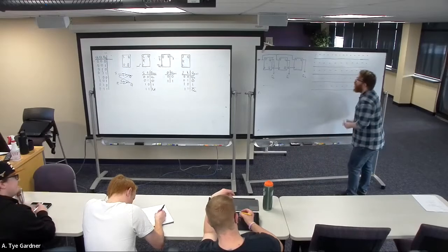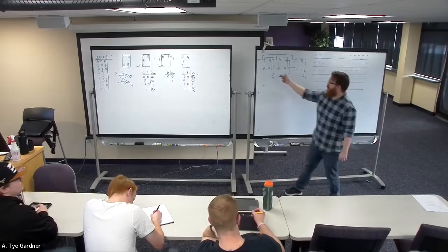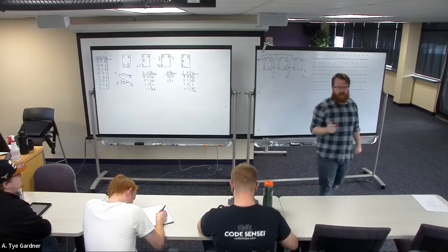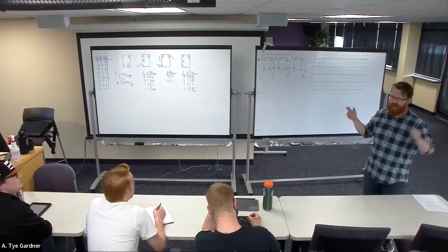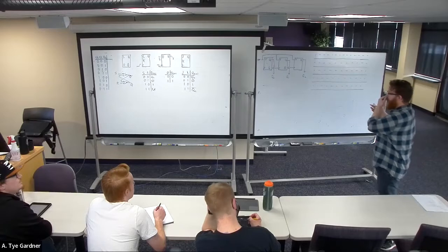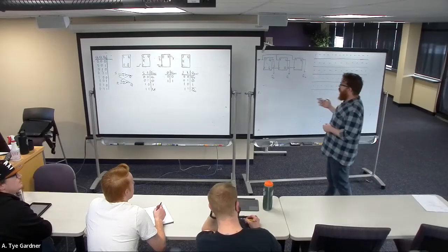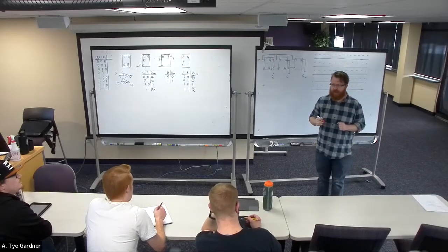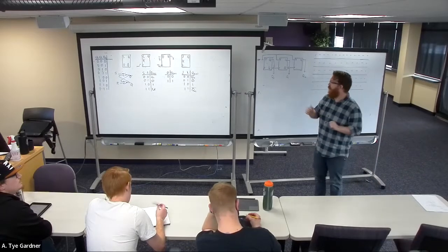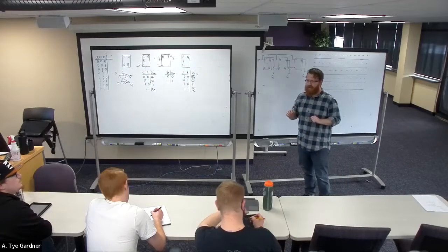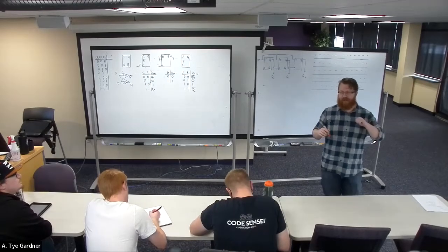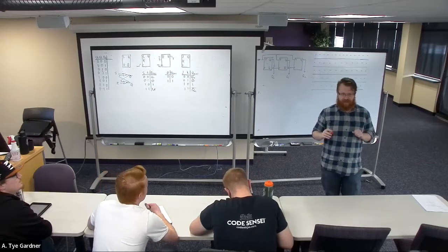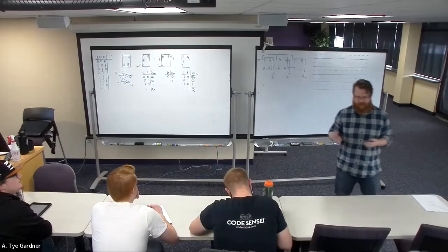Okay. So let's just assume that enable is going to be on. We'll just say enable is 1, so I don't have to use a whole line for it, because if it's not enabled, nothing happens. The next thing is, in the case of a T flip-flop, I have to give you the starting values. I have to tell you what the output Q starts at. Because if I say it's undefined and you want to toggle it, what is not undefined? It's still undefined, right? We still don't know.